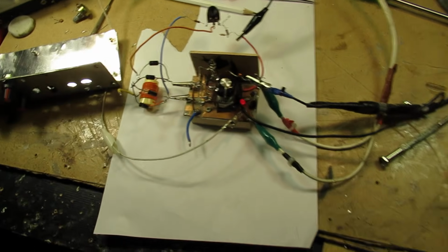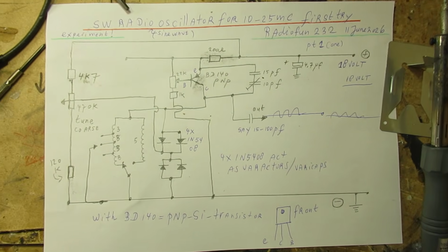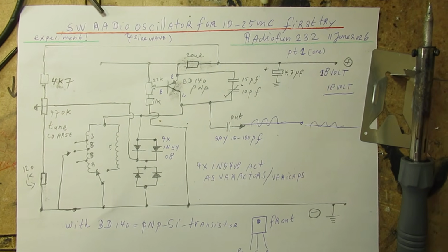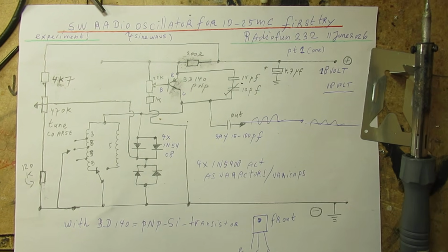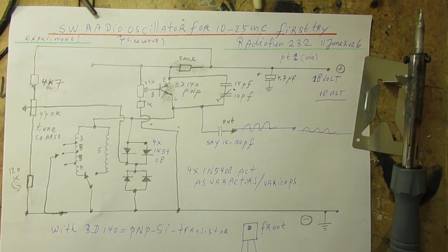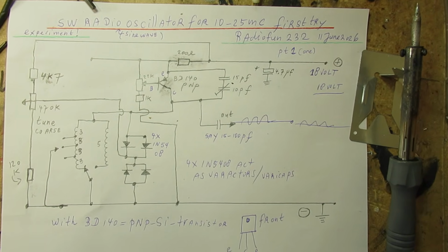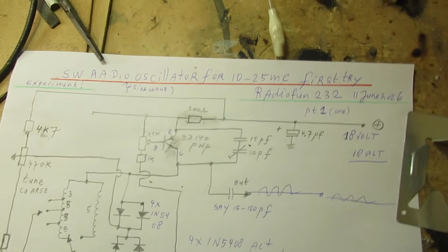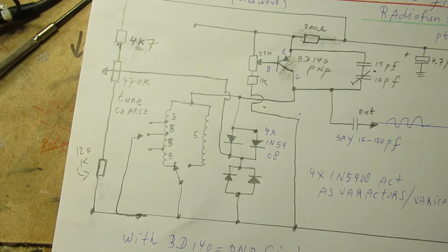It is, in my opinion, a quite good experimental circuit for radio applications, a sine wave oscillator in that higher frequency band, say 10 megahertz up to approximately 20 megahertz or perhaps even higher, and that depends on the coil that you use here.